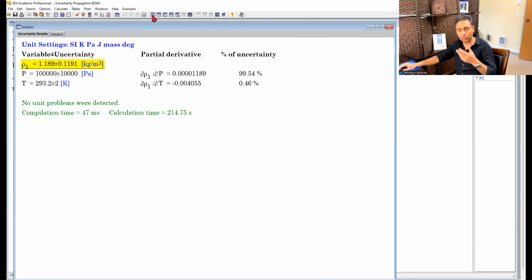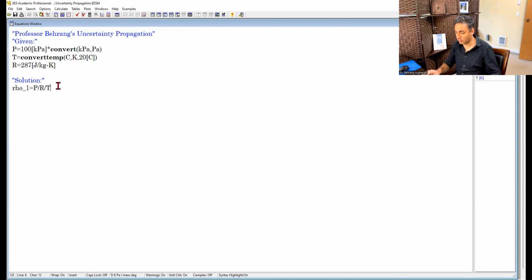You might say, okay, so this is for equations. EES uses a lot of functions to find enthalpy, entropy. What if, instead of using the ideal gas law, I use the EES model for density that uses the ideal gas law? So I'm going to call it rho 2. Rho 2 is the density of air. Air is the ideal gas model of air for EES. Temperature is T, and pressure is P. The P and T we defined.